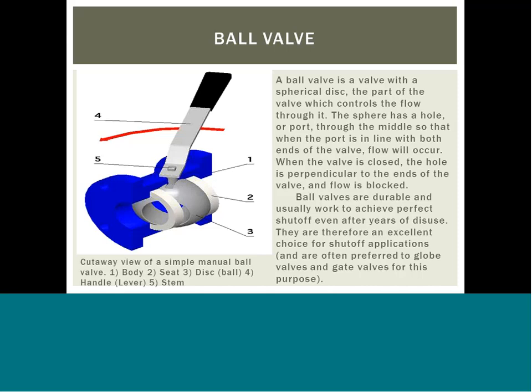They are therefore an excellent choice for shutoff applications and are often preferred to globe valves and gate valves for this purpose. They do not offer the fine control that may be necessary in throttling applications, but are sometimes used for this purpose.